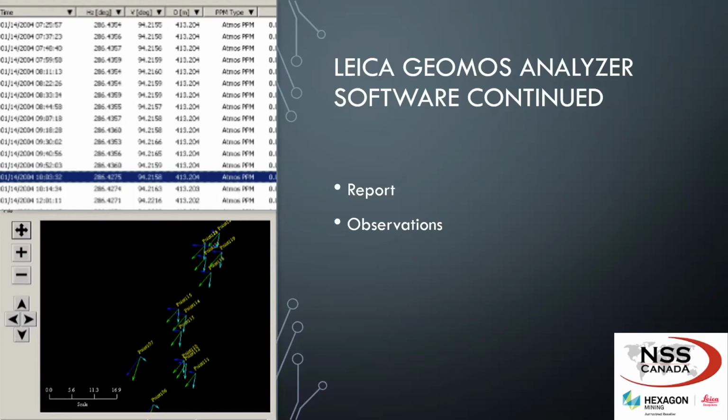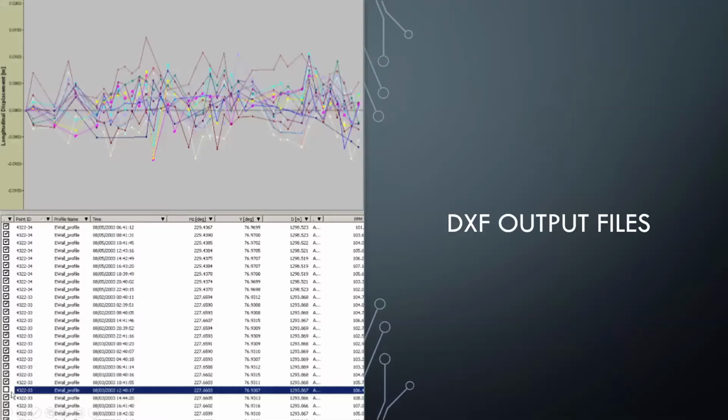Leica GeoMoS does need some time to gather accurate and true displacement and deformation. This is due to many reasons, such as adjusting to the actual movement of the structure, such as a building swaying, even slight wall movements in the open pits and so on. By the time of full install and getting reporting numbers, I'd say we're looking at about a month for true displacement numbers. In the next slide, I believe you're going to see a little bit better.